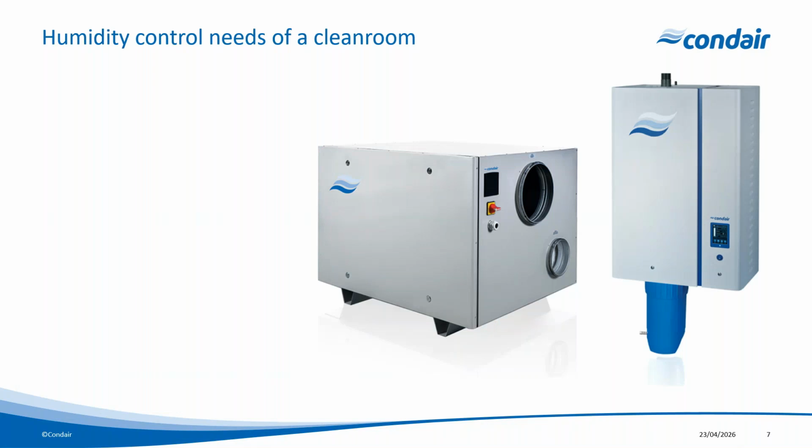With a dehumidifier, typically we're taking the air from the space, from the clean environment, putting it through a dehumidifier, drying it, and then putting it back into the space. Now, as we're only taking it from a clean environment, and the only risk is any particulate that could come from the silica rotor, typically we've also got a filter on the outlet side of the dehumidifier, so it's very, very small risk.